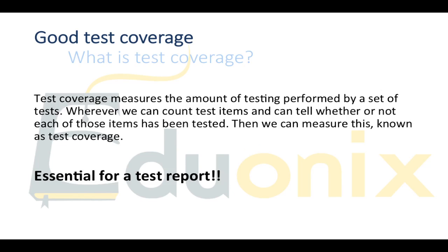How do you ensure that the test meets the test quality and coverage needs of the design, especially in common situations where the board designer and the test developer are from 2 different companies or even 2 different sites? Well, test coverage measures the amount of testing performed by a set of tests. Wherever we can count test items and can tell whether or not each of these items has been tested, then we can measure coverage. This is known as test coverage, which is essential for a test report.